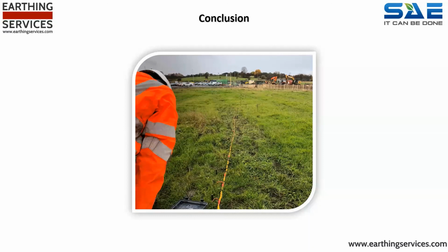So, how resistant is the ground? How much of it can we use? What conductors will we put in it? In what kind of orientation? And how much of the conductors are there? The first step is the soil model. And if we do not know how well it discharges current, everything after it is speculative.